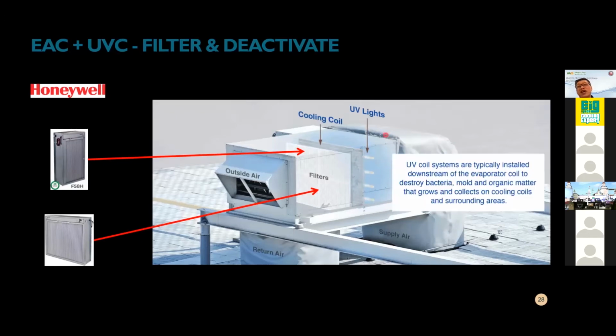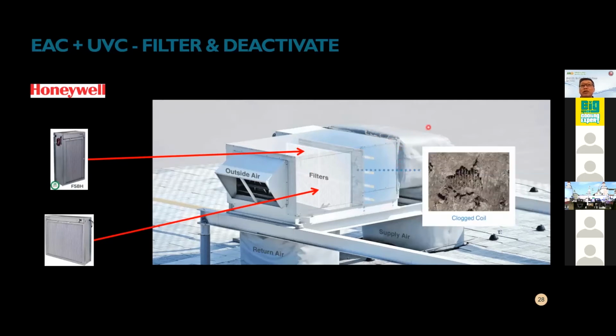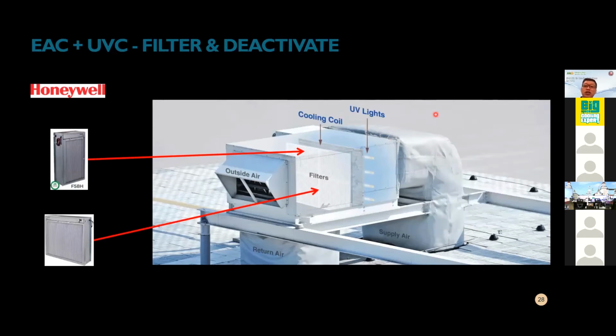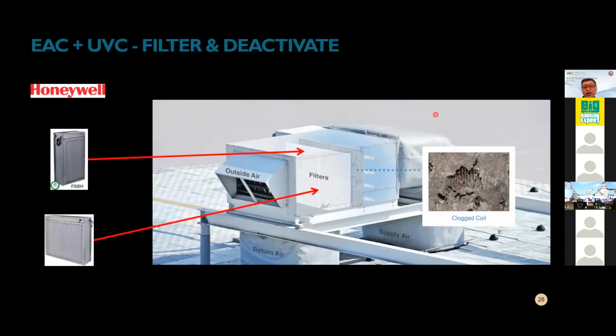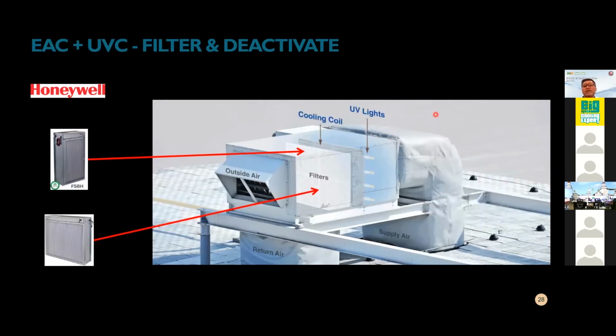The reason why a combination will work better is because studies have been done, and certain research also shares a table of combinations. For the UVC lamp there is the URV, ultraviolet rating value. So it's like MERV, where MERV is for filters. They have to combine both in the same standard, then only will it perform effectively.